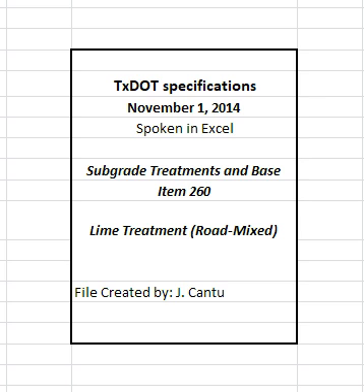3.1 Storage facility. Store quicklime and dry hydrated lime in closed, weatherproof containers. 3.2 Slurry equipment. Use slurry tanks equipped with agitation devices to slurry hydrated lime or quicklime on the project or other approved location. The engineer may approve other slurrying methods. 3.3 Provide a pump for agitating the slurry when the distributor truck is not equipped with an agitator. Equip the distributor truck with a sampling device in accordance with TEX 600J, Part I, when using commercial lime slurry or carbide lime slurry.